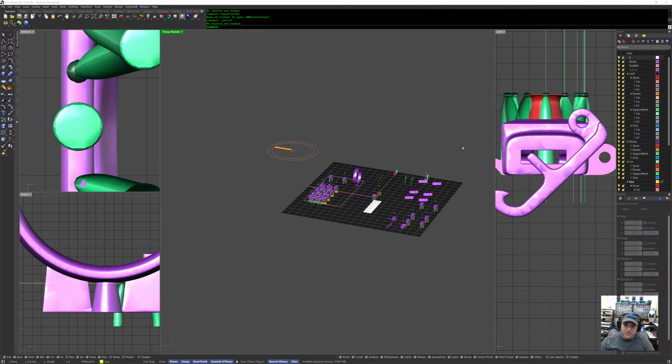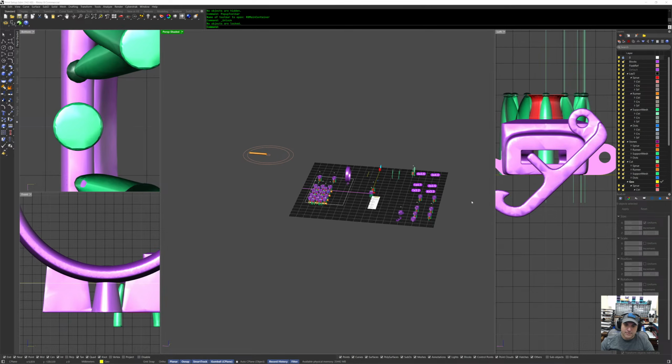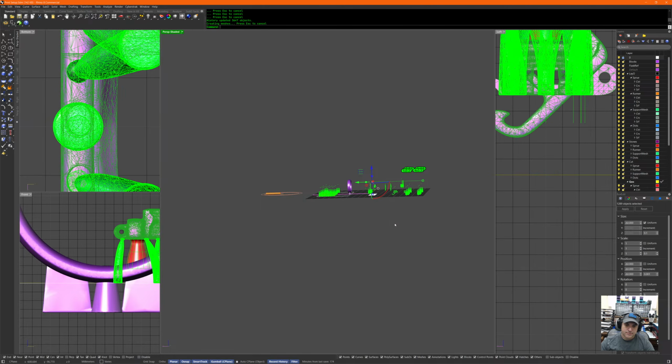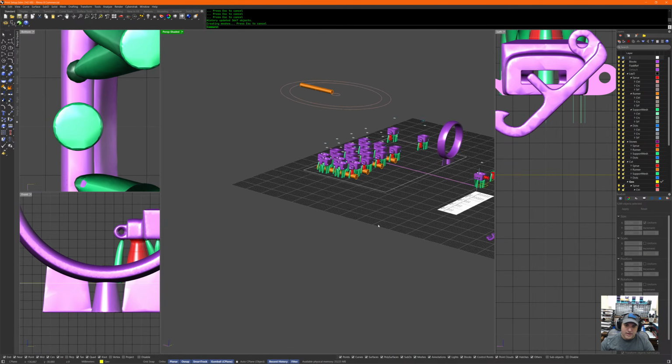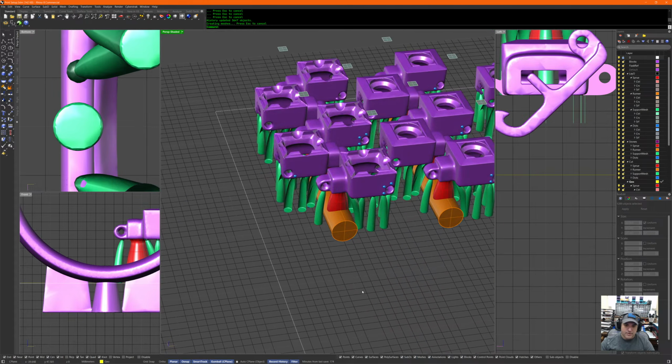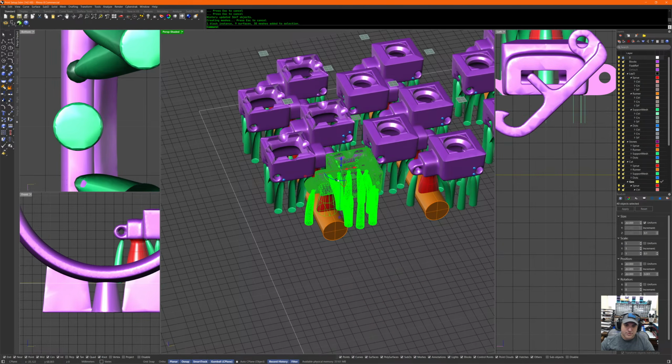I'm going to lock my 0 layer, which is this stuff, because that can stay flat. And then just grab everything and say, not the ring because I already moved that up to 0. Grab everything and say move up 5. And that's an awful lot of history to replay, but everything moved up. Everything still has history on it.